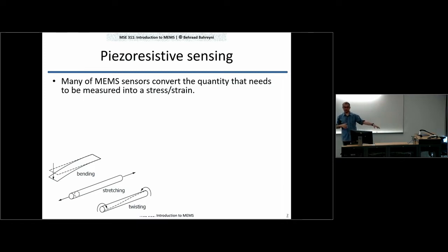So through that mechanism, you can actually measure pressure if you could measure the strain at the edge of the membrane or anywhere else, as long as you just want to do a measurement, but the optimum location is around the edge.